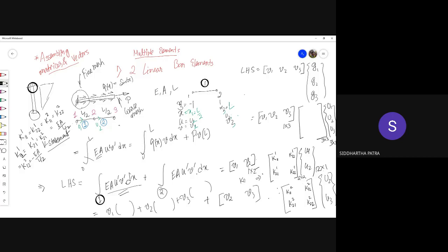So if you have already got the coefficients of v1, v2, and v3, which are some g1, g2, and g3, so I can write in this format, which essentially is a dot product, okay, and then write this vector as this part. So this second vector basically contributes to this matrix and u1, u2, and u3. I need you to give me this matrix, and this matrix you would call the global stiffness matrix.